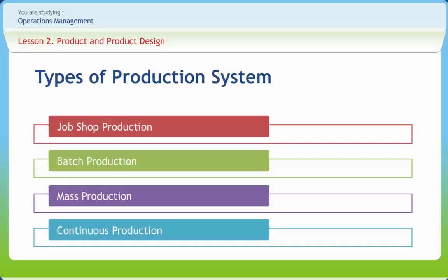Manufacture of discrete parts or assemblies using a continuous process is called mass production. This production system is justified by very large volume of production. The machines are arranged in a line or product layout. Product and process standardization exists and all output follows the same path. Production facilities are arranged as per the sequence of production operations from the first operation to the finished product. The items are made to flow through the sequence of operations through material handling devices such as conveyors, transfer devices, etc.